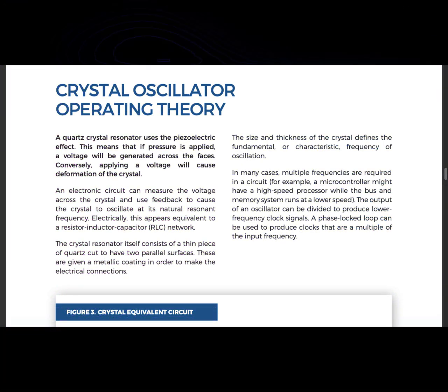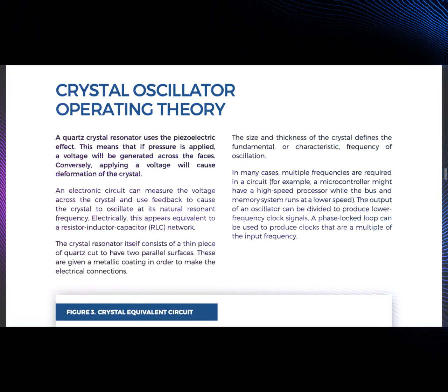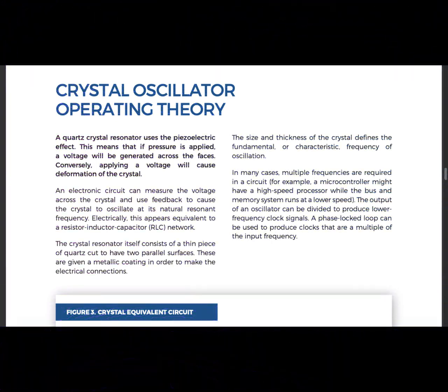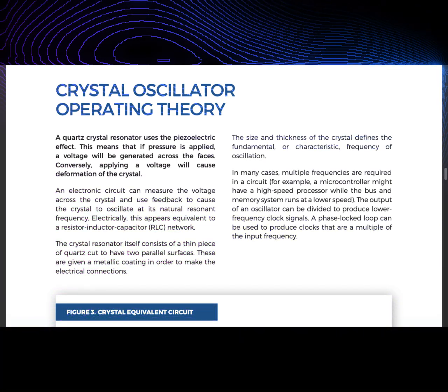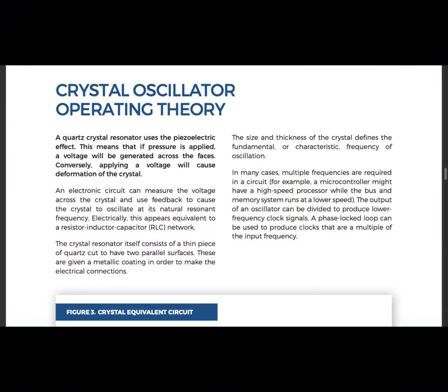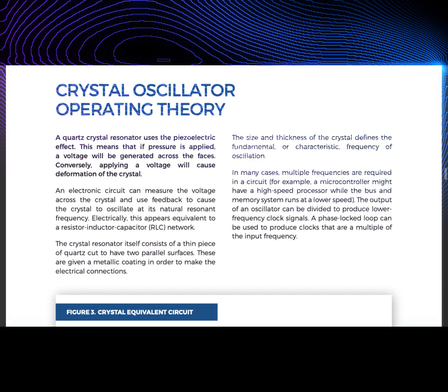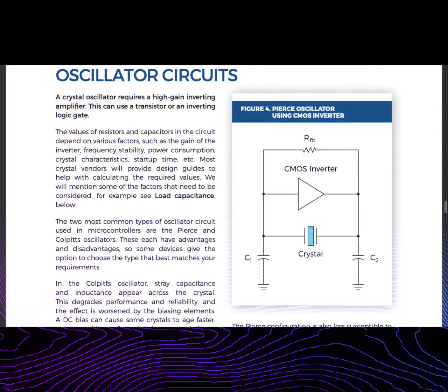Seed quartz crystals with the desired crystallographic structure are placed in the upper chamber of the autoclave. The bottom of the autoclave is filled with crushed crystal material in an alkaline solution, to serve the crystal growth onto the seeds.